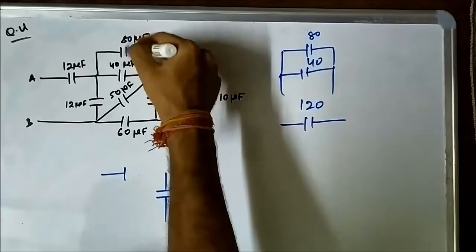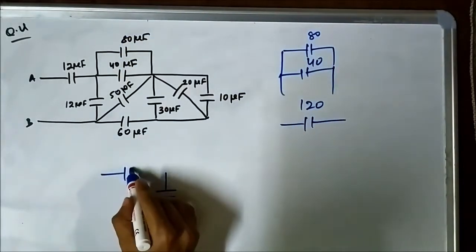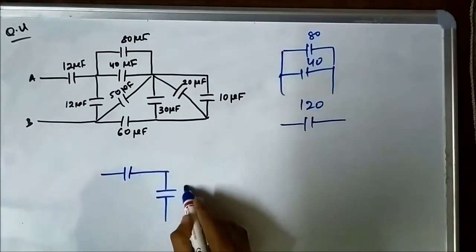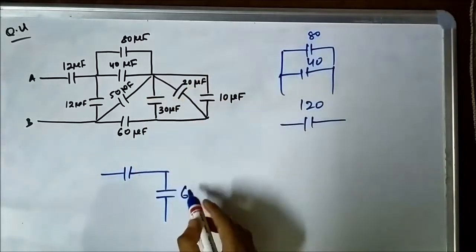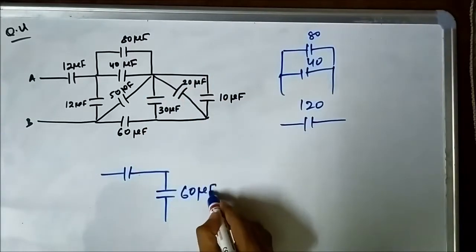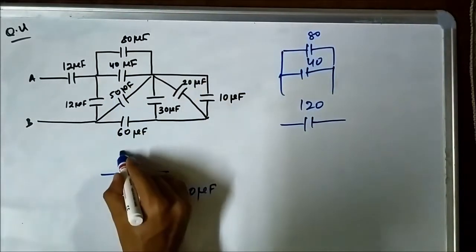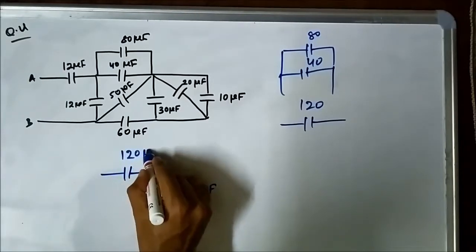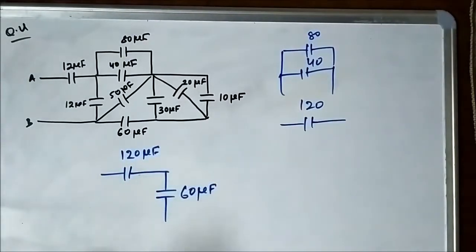So we can just replace these three capacitors with a 60 microfarad, and these two capacitors with a 120 microfarad equivalent capacitance.